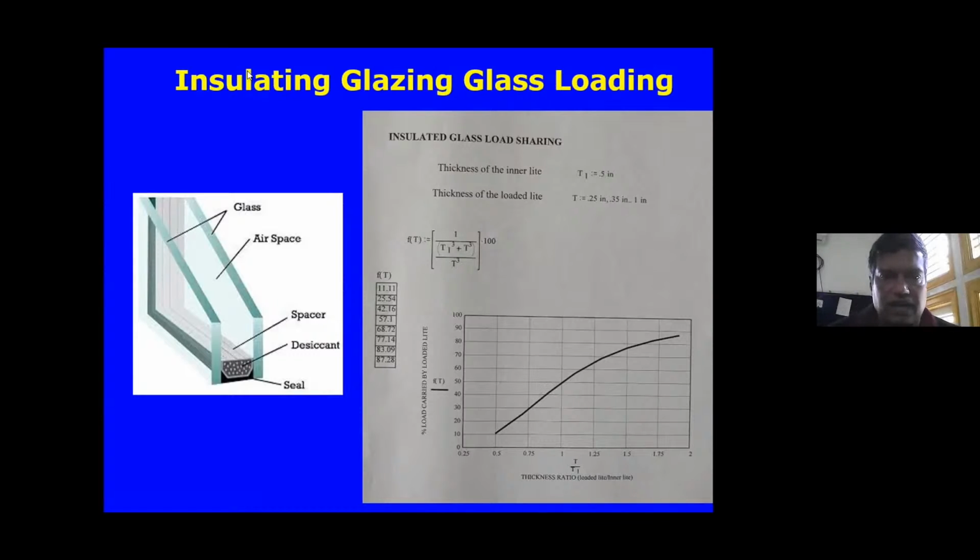So if the two glasses are the same size, they probably take the same load, meaning the front glass gets a load of about 100 kg per square meter of wind load. Each of these panels would share the same amount of load because they both have the same stiffness.